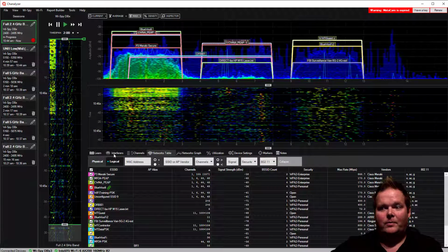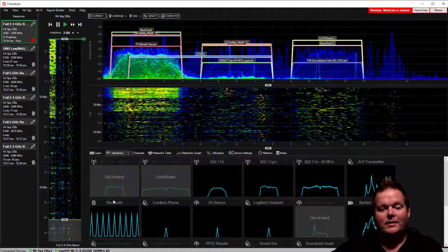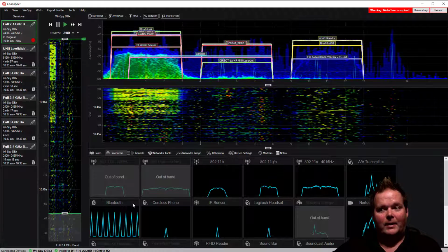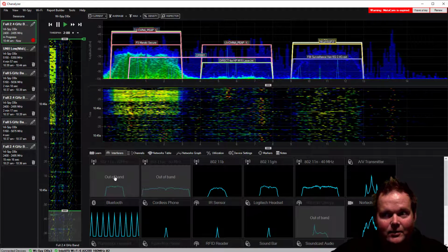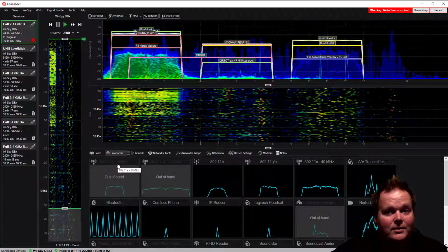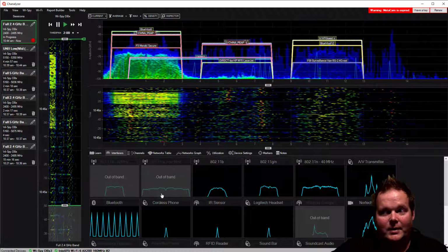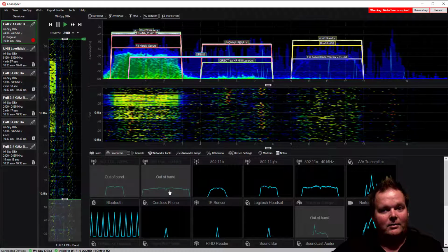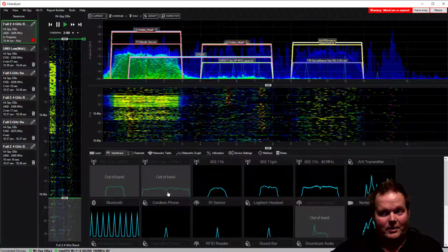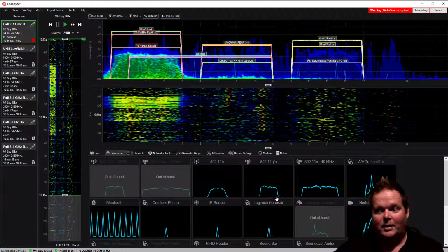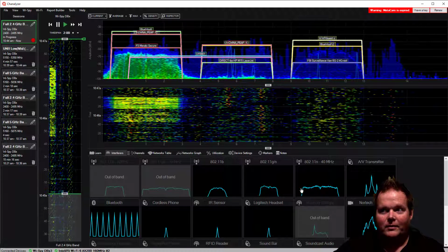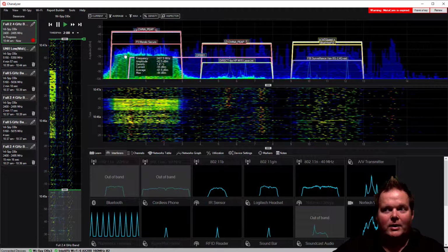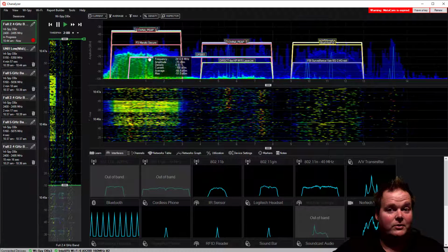Okay, so back over here under interferers, this is a list of known interference sources for 2.4. If it says out of band, look at the ones that say out of band. That's 802.11a. That's an OFDM waveform. If we look at AC, that's a bonded OFDM waveform. You've got that Bart Simpson haircut with the little dip in the middle. That's OFDM, right? You double that, and that's channel bonding. But then we've got all this other stuff, right? We've got 802.11b, it's going to look like that dome top. Well, I don't really see that dome top here, which is good.